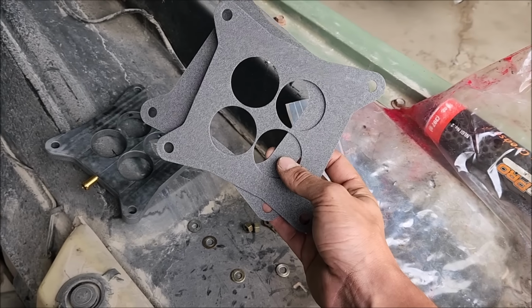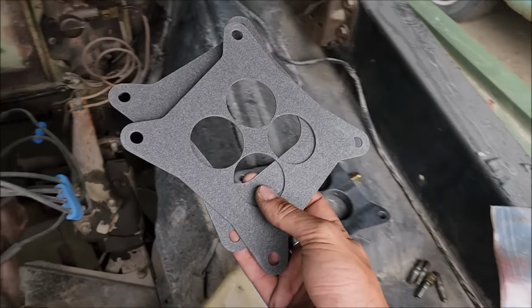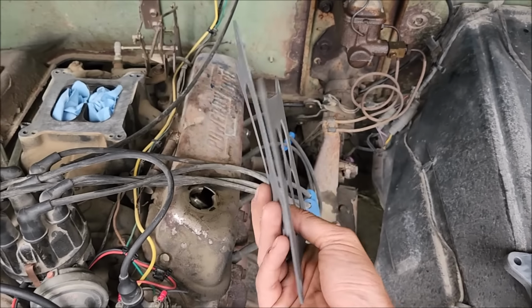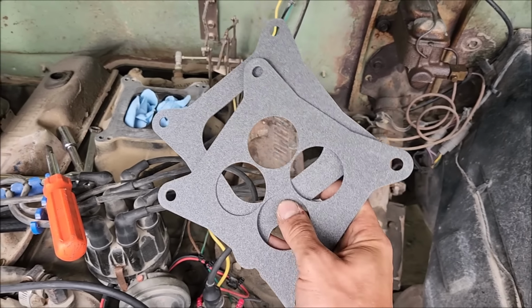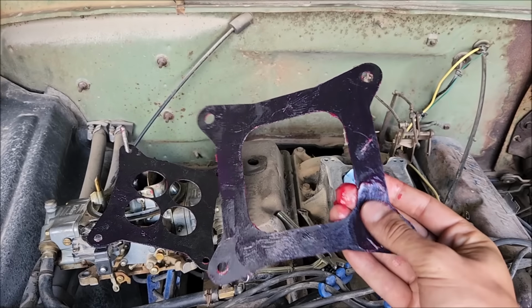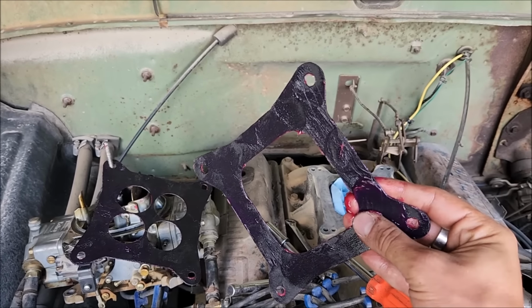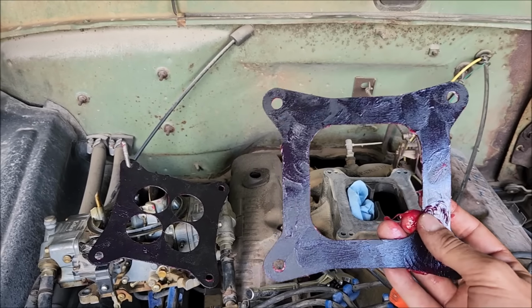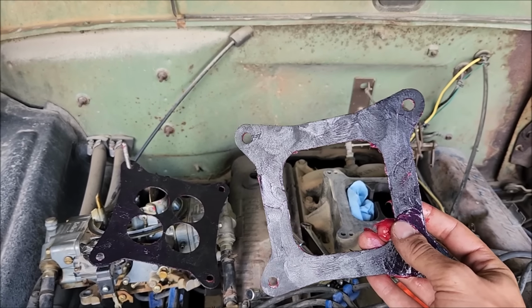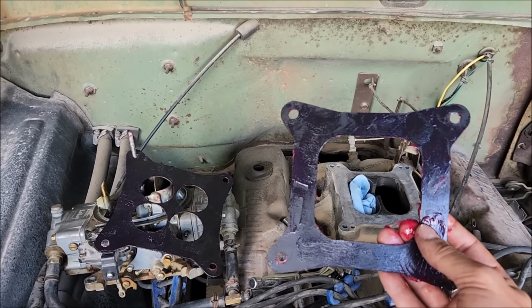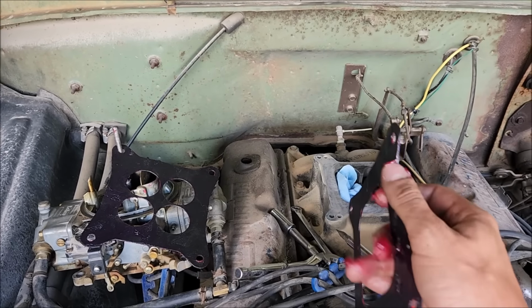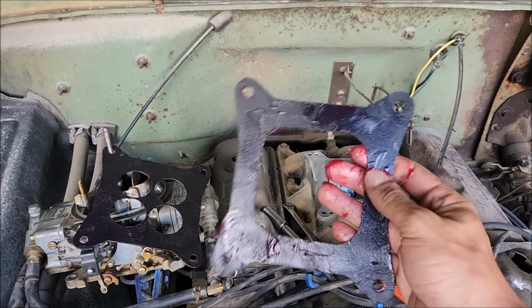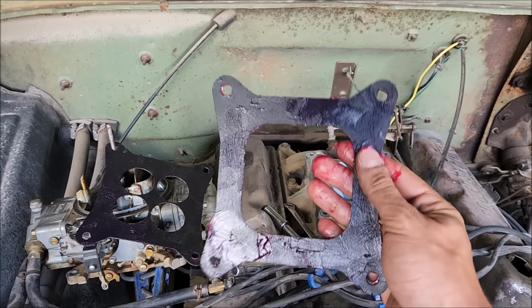It just seems wrong at the time, but I'll tell you what, you go to take these off 5-10 years later, they come off in one piece, and basically you can even reuse them. Now this is gonna feel weird and dumb, but I promise you, you'll thank yourself later. And don't be tempted to wipe off the excess, because after this thing goes through a heat cycle, this will all soak into the gasket, and it'll do a really good job of basically immortalizing the gasket forever.